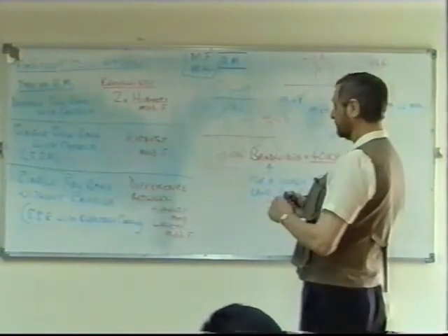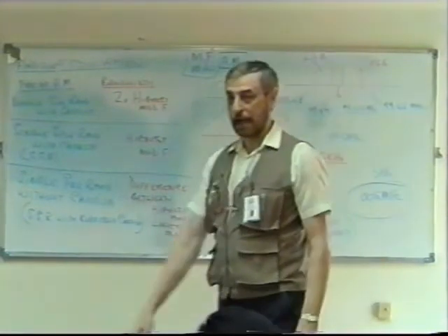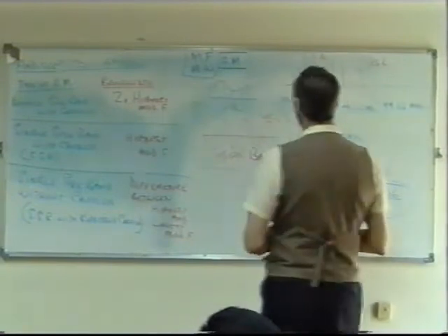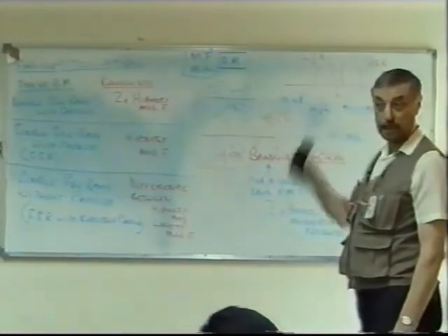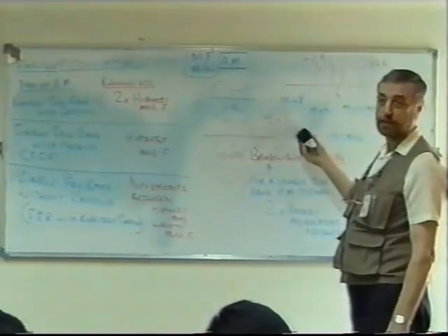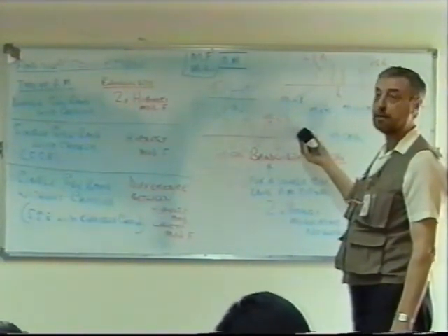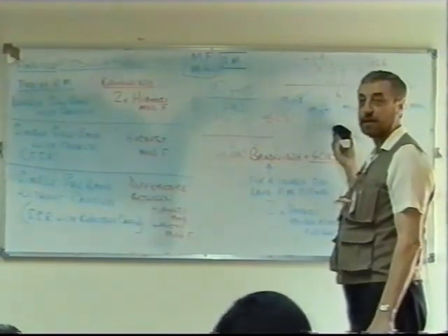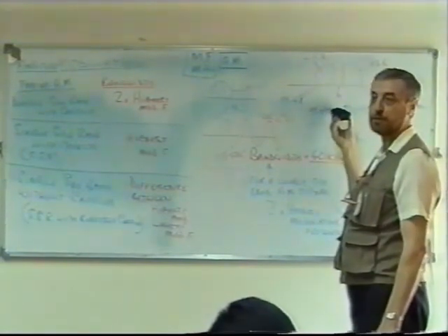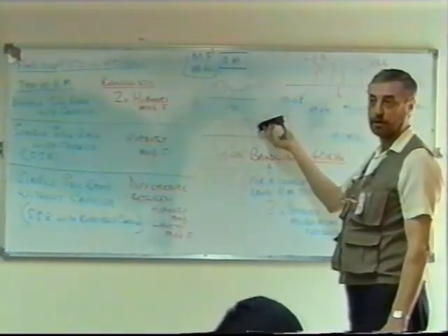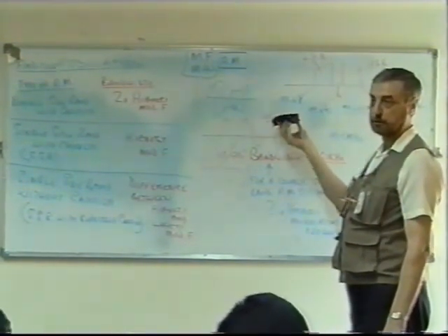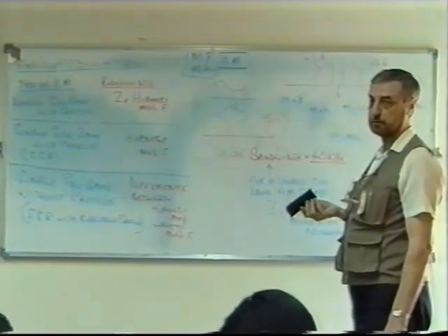The type of modulation is still amplitude modulation, but when you cut out certain frequencies from the output of the amplitude modulator, then the wave changes in nature, but it doesn't become FM. FM is where you change the frequency of the output according to the amplitude of the input. Here, the frequency of the output depends on the frequency of the input. So it's not FM, it's AM.